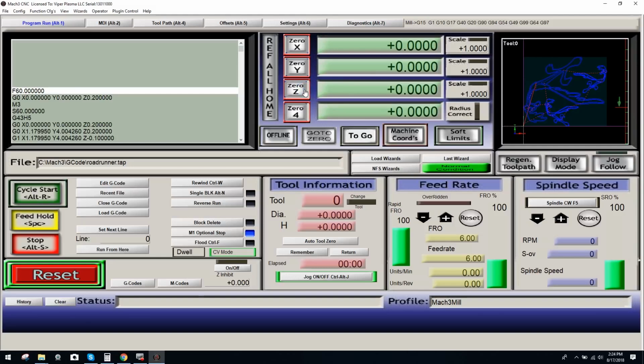Boom. Okay. Now what we're going to want to do, being we have our new zero starting positions for G54, which is the default, once again, the default offset we're in, we're going to want to go the opposite direction. Okay? And this way we get an accurate measurement of where we are. So now we'll want to move over in the opposite on the X, and we'll just go. And again, I'm doing this just like you would do it. Okay, you're going to check, you're going to watch a table.